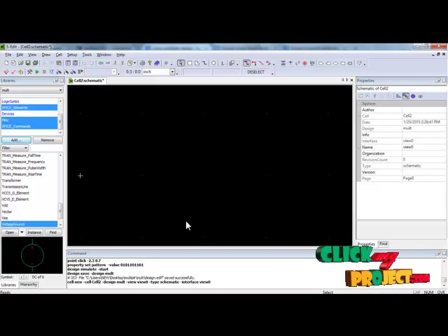After designing this cell, you can save the design, and when you press run, it will lead to T-Spice. Through T-Spice, you can see the netlist available. In T-Spice, usually the components which you have used are listed as component code. That means you can see it program-wise. That's why those T-Spice codes are called netlist. You can run either from SEdit or from T-Spice.